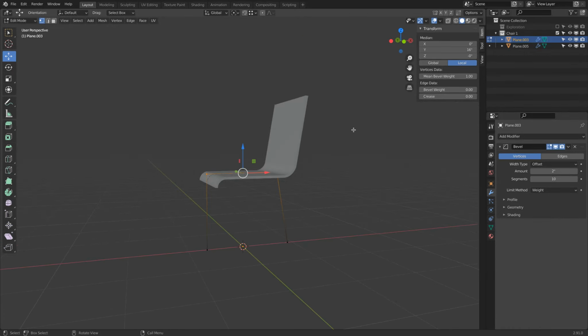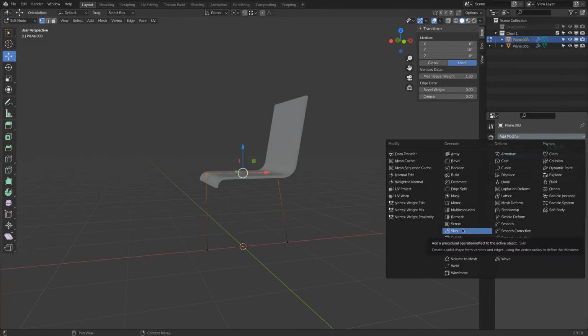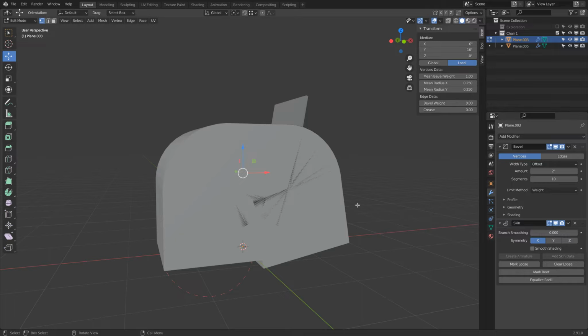Cool. Now, how do we give this a thickness? There's a skin modifier, which is very useful for visualizing piping really fast. The pipe this skin modifier creates is square in its cross section. It's not necessarily, again, super precise, but it is very fast to work with. In Fusion, when we do piping, you will see this is actually quite labor intensive. So it's all about speed and understanding versus perfection. So we go skin modifier.